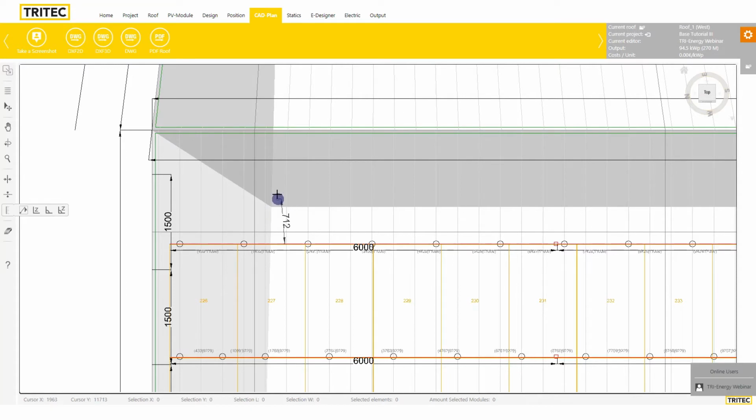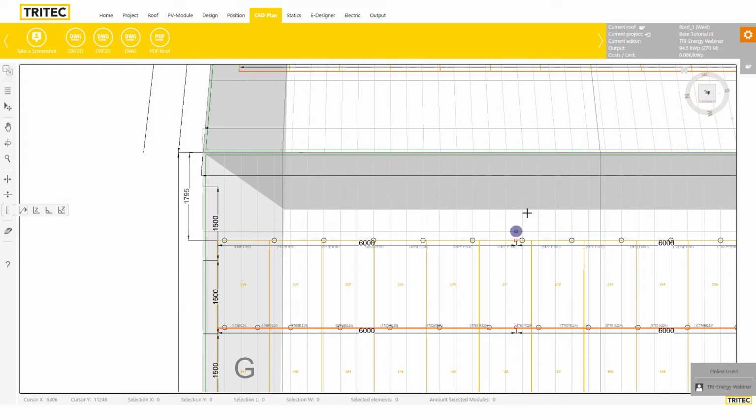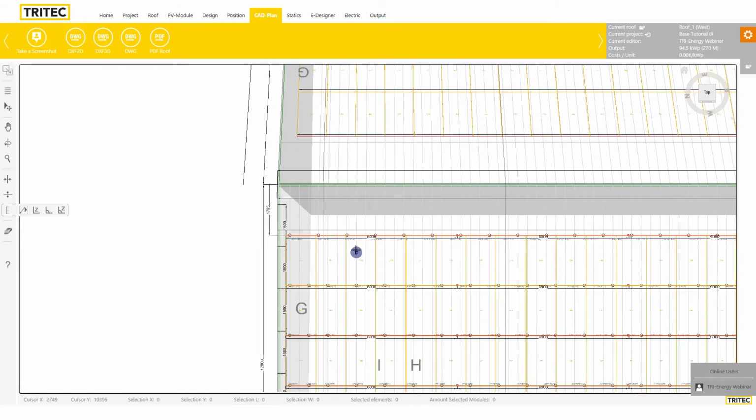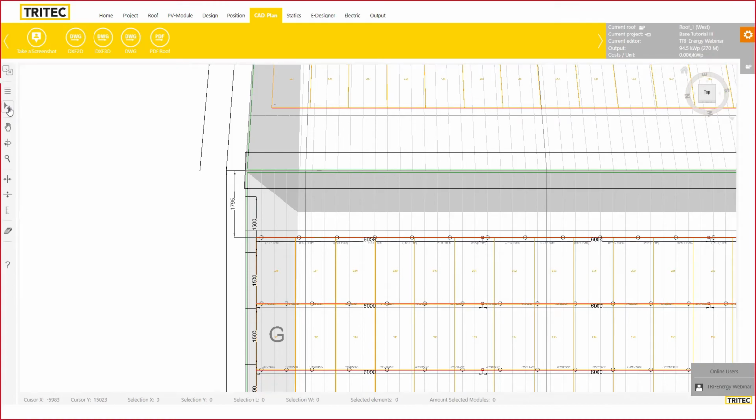So the first click starts the drawing, and now you're totally free, which in this case is not really precise. But once I have hit the shift key, I'm limiting the orientation to either perpendicular or parallel, horizontal or vertical. And then the docking, that's nice. The second click is stopping the measurement. The third click is determining where the measurement will be displayed later. So you could take your measures at any time.